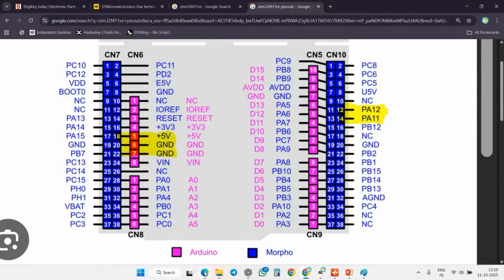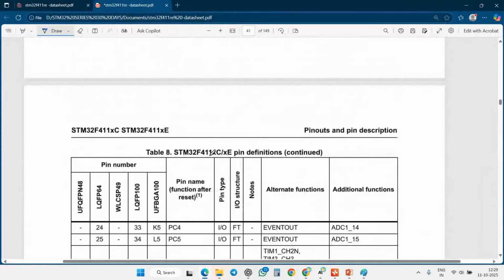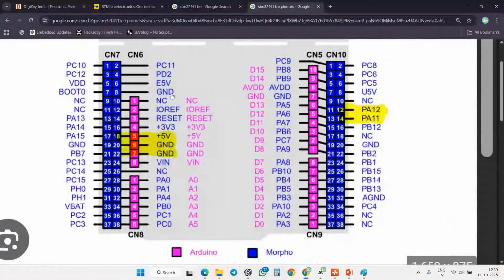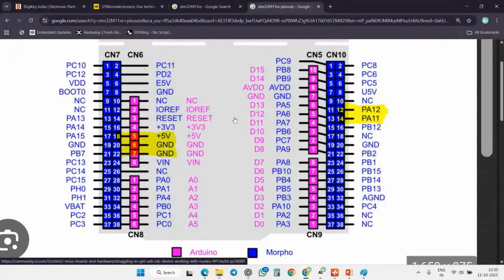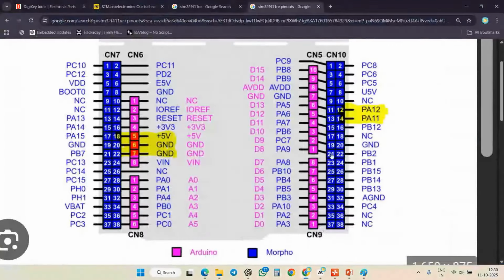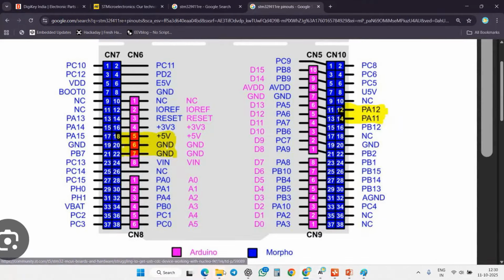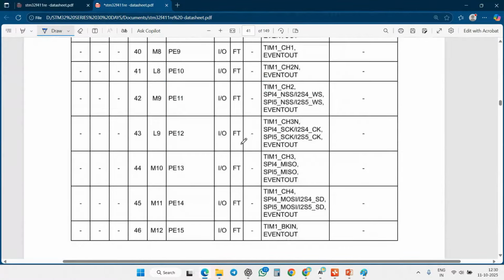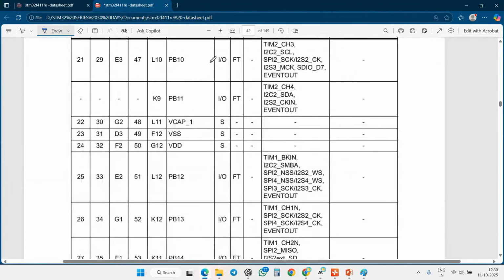So this is exactly what this pin configuration gives, guys. If you take PB1 and refer to this, what is the purpose of PB1? You can get all that data there. PB1 is pin number 24. If I simply look at my microcontroller's GPIO, I can't recognize the functionality. You need to refer to this. You can configure timer, SPI and event out. For everything, you look it up like this.